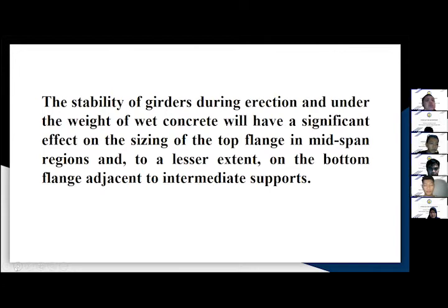The stability of the girder during erection and under the weight of wet concrete will have a significant effect on the sizing of the top flange in the midspan region and, to a lesser extent, on the bottom flange adjacent to intermediate supports.